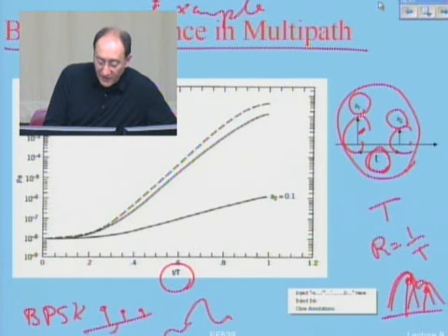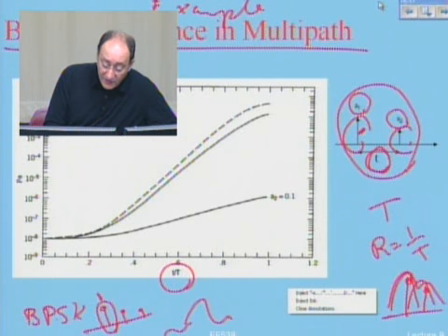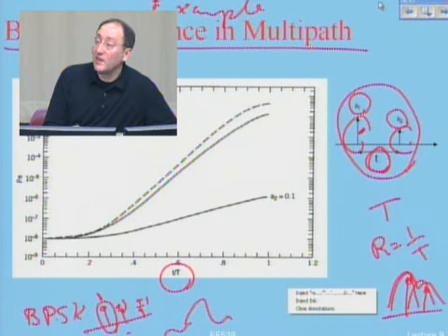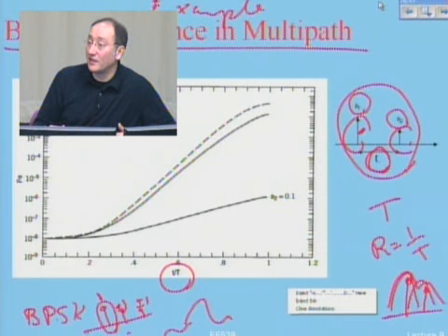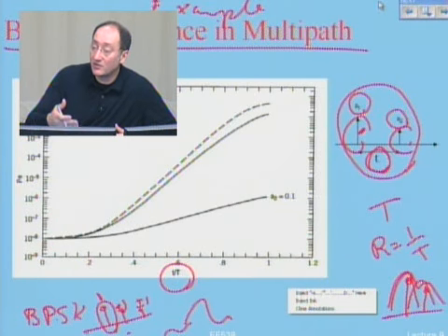And then, whenever this symbol is binary PSK, whenever this one is 1, I may have this neighbor be either 1 or minus 1. So they may add to that or they may subtract from that. They may add to my signal-to-noise ratio.